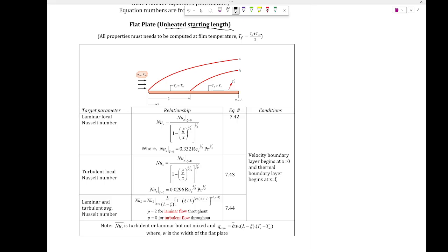Say you have some coil sitting here, and this coil is producing constant heat flux, or you have a different temperature here compared to here, right? So what will happen when the fluid flow comes on top of it? Because this zone has a constant heat flux or constant surface temperature, the heat transfer starts from here, not here, and that is what you are seeing here, right?